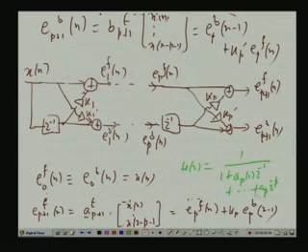Now, this is the all pole transfer function. For this model to be viable, that is stable and causal, the poles must lie within the unit circle, and we will show that by solving the Yule-Walker equations. Whatever coefficients you get, those coefficients a_p1, a_p2, up to a_pp, indeed ensure that the corresponding poles are within the unit circle.